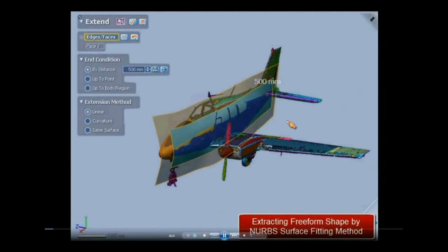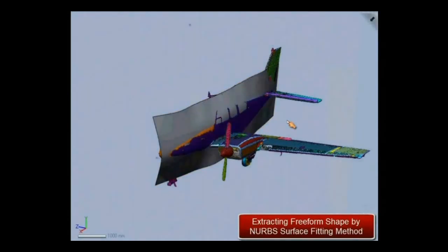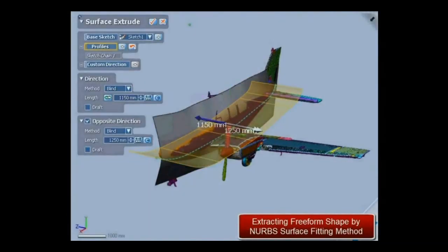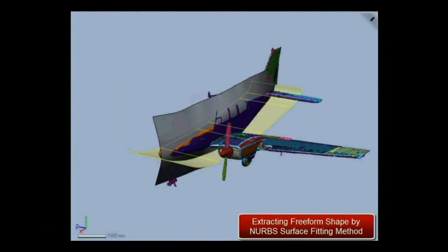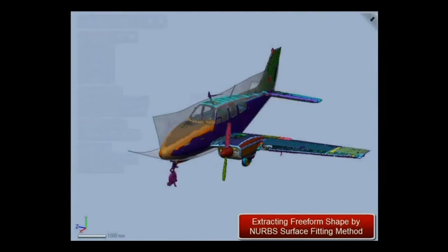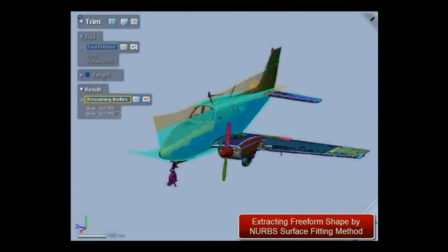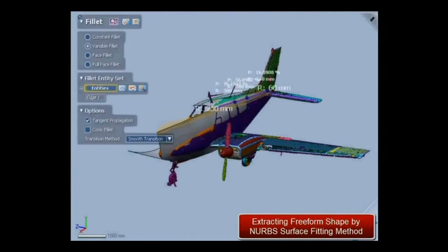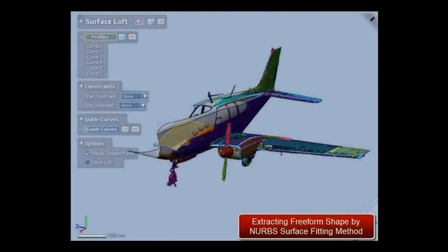We are using basically loft, and we have a loft wizard as well, so we can generate multiple sections through the airfoil. We can also generate sections along a plane, facing a plane, or we can create sections along a curve. So if the airfoil is bent, then we can also define a skeleton curve, and then along that skeleton curve we can create the loft sections.